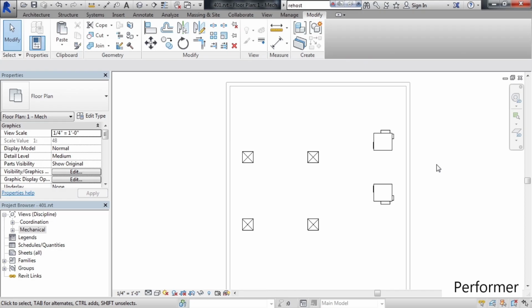So in this lesson, we looked at mirroring objects, starting by selecting an object first, then choosing your mirror tool. We also looked at starting the mirror tool first, then selecting an object. We also looked at the 2 types of mirrors, picking a mirror line from something that already exists, let's say an edge or the center of a wall, or creating a mirror line by picking 2 points, defining that mirror line wherever you like.